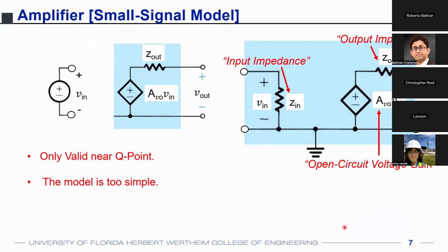All right. And again, as the question was asked, here you see a Thevenin equivalent model where you are representing the voltage gain times V in, and you have a series resistance over here. You could have represented this as transconductance times V in with a current source and then a parallel resistance. That would have been the Norton equivalent circuit, which is your homework problem 5 in your homework 1.